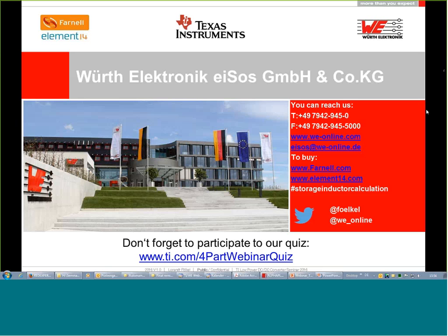So definitely, if I would use a ferrite bead, which works for losses higher than around 10 megahertz, I don't think you will need to put one on the output of the buck converter. I will use it maybe on the input. If you have a nice input filter on the buck converter, I will definitely use it on the input.